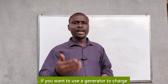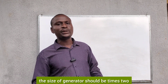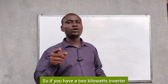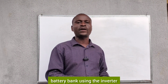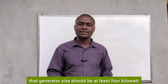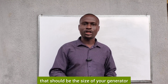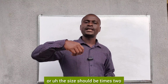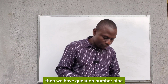Now, if you want to use a generator to charge your battery bank using an inverter, the size of the generator should be ×2 or ×3 the size of your inverter. So if you have a 2 kilowatt inverter and you want to use a generator to charge your battery bank using the inverter, that generator size should be at least 4 kilowatts. That is 4 to 6 kilowatts. That should be the size of your generator. So the size of your generator, once again, should be ×2 or ×3 the size of your inverter.